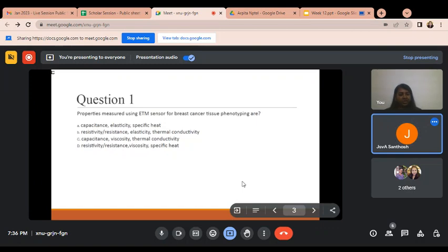So we will continue. In the photolithography process, first a deposited material is present, like silicon dioxide or something else. Then we have to transfer a pattern from the mask to that layer. So at first we will cover the surface of that deposited material with photoresist.